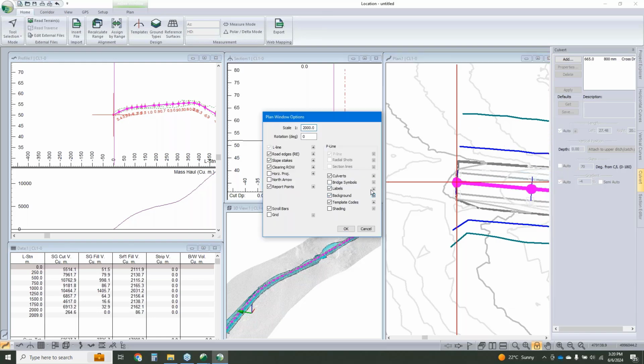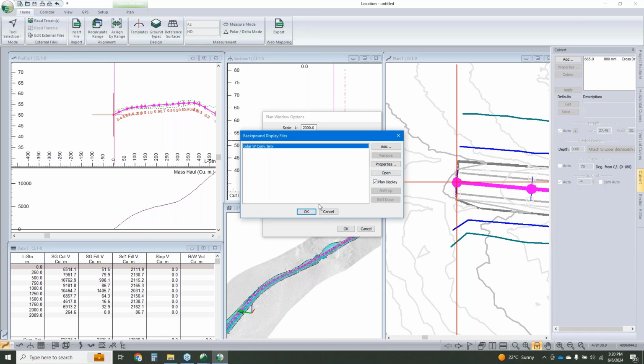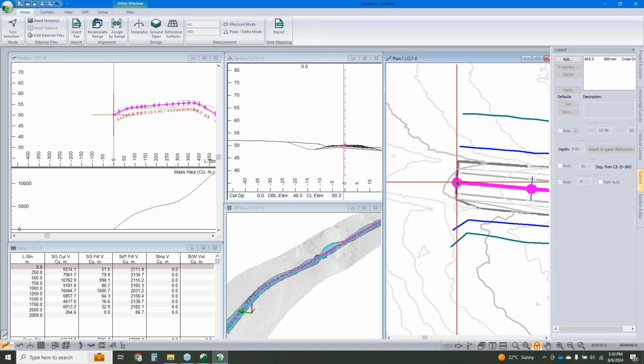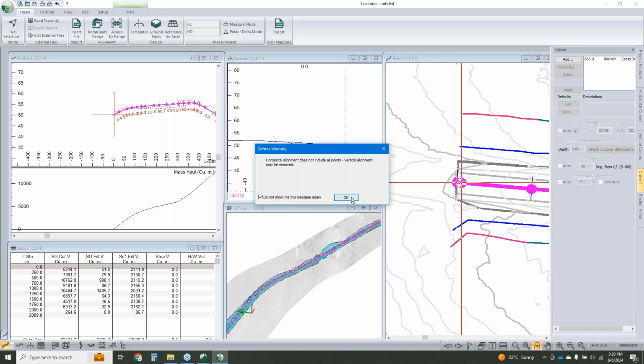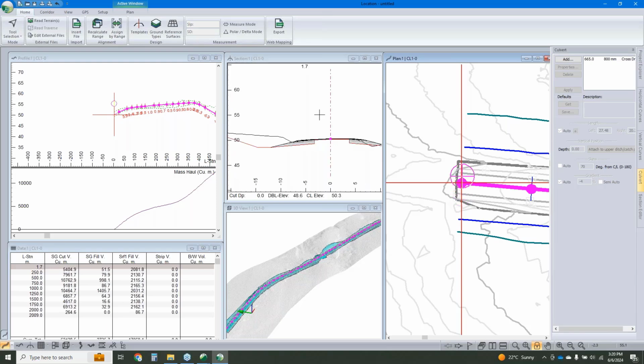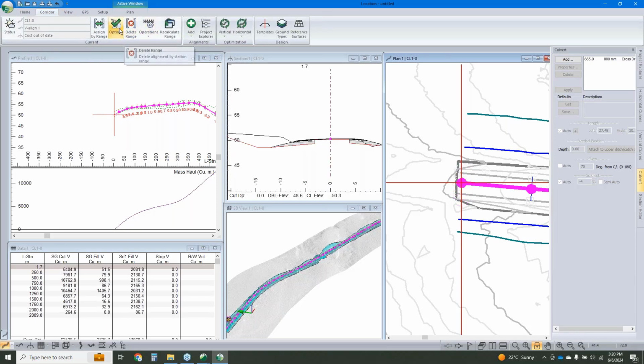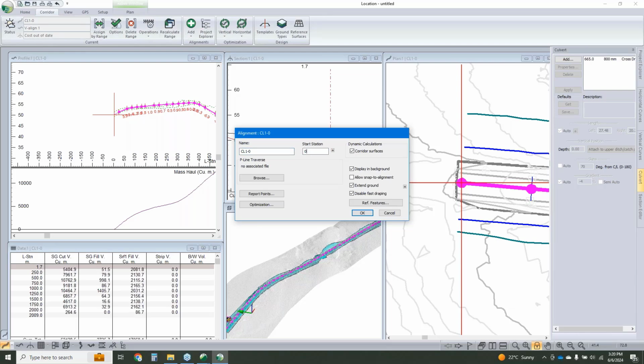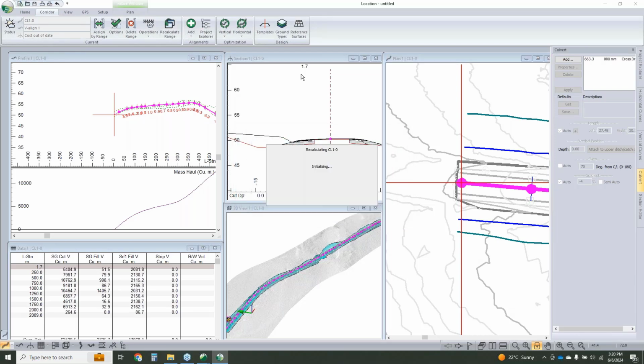I could change my template so it's not set to a reference feature, or I could just move my start of my road a hair to match what I'd like. So it lines up with that surveyed feature that we'd like to reference. And there we are. And here, if we want to change that to be our 0 station, we can make that change, and now our start of a road is at 0 the way we'd like it.